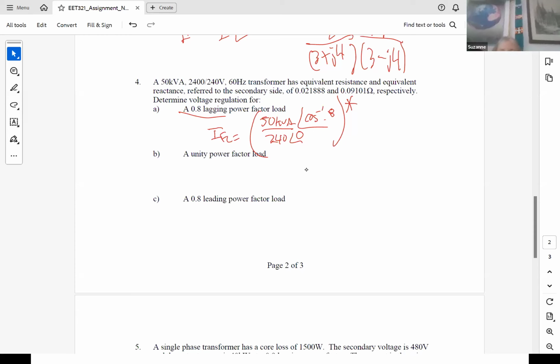Yep. Now, if you're at the utility levels, they'll have different rules. Their voltages have to be able to go up to plus or minus 10%. They could run at a much bigger range. And that's because the customers have a tighter range. So I have to push my generators and my transformers much harder to be able to make the systems work. So generators, transformers, they operate at a much wider range. It doesn't sound like much, but going double is actually quite a bit.